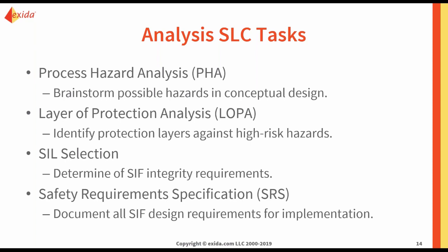For IPLs that are SIFs, you want to determine the integrity requirements for those SIFs so that the design team knows what to design to. So that's done in your SIL selection. And then you want to document all SIF design requirements for implementation. You want to be compliant with IEC 61511, so you want to address each requirement that it lists as important to include in this specification. And so that's your safety requirement specification task.